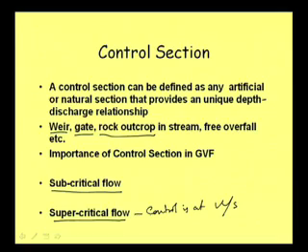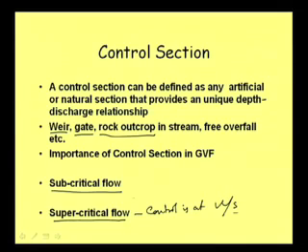Of course, indirectly it can influence. Suppose something we do at the downstream point has made the profile become subcritical downstream. Then that subcritical flow will be affected by the disturbance we are making downstream, and this may indirectly reduce the portion of supercritical flow, and hydraulic jump sorts of things we can get. We will discuss that later, but for now we can just note that control is at upstream for supercritical flow, and in subcritical flow control is at downstream.